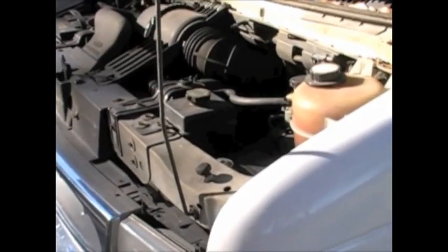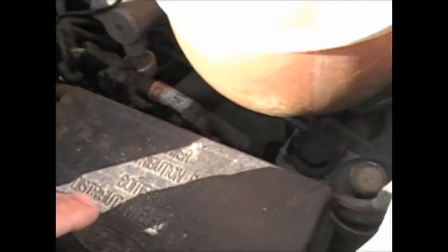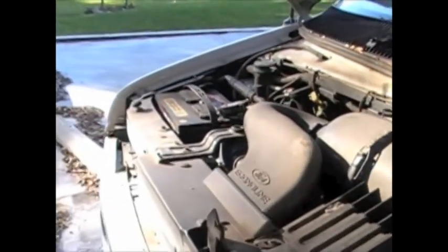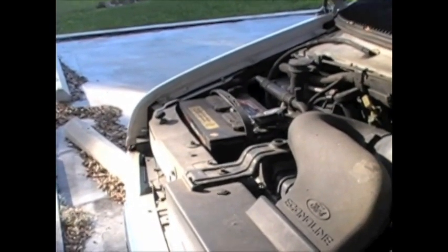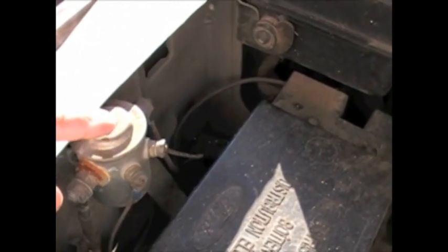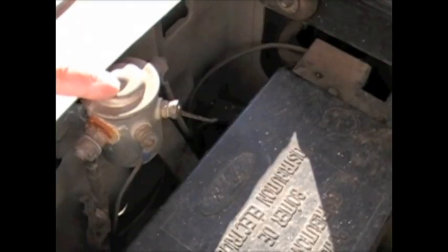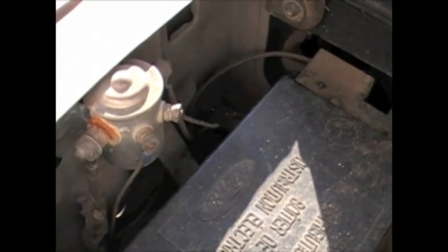Okay, here at the front of the truck, I'm going to go ahead and show you this relay that I was talking about. You can see here on this side of the van is the power distribution box. And then on the other side of the van over there, we have the battery that actually operates the van. But here, you can see the relay that I had installed, which when the truck is running, the relay will make a complete circuit and power will feed to the battery in the back of the van to keep the battery charged.